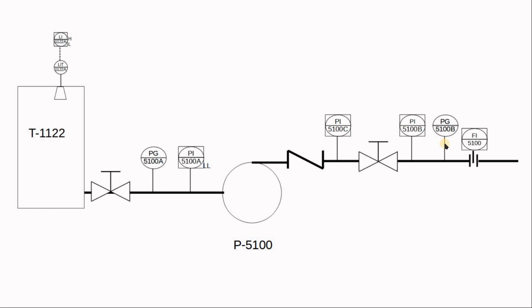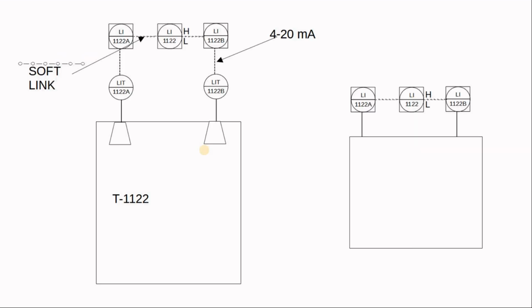Again, I have discharge gauge and flow indication. So this looks like it is flow based on an orifice flange orifice plate, and a differential pressure transmitter goes to the DCS with a flow indication. You have the transmitter, and the dotted line means you have electric signals. In our case, it could be 4 to 20 milliamps.